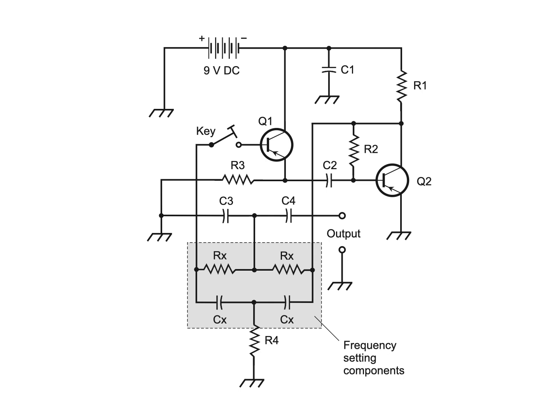This circuit uses a 9-volt battery as its power source. Note that the transistors are of the PNP type, so the collectors get a negative voltage, while the positive battery terminal goes straight to ground. This circuit, therefore, constitutes a positive ground system.